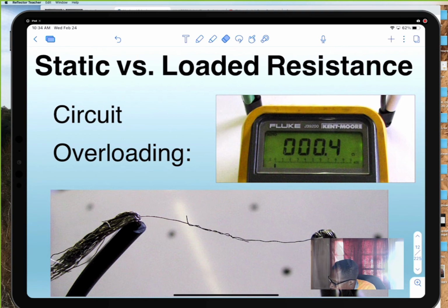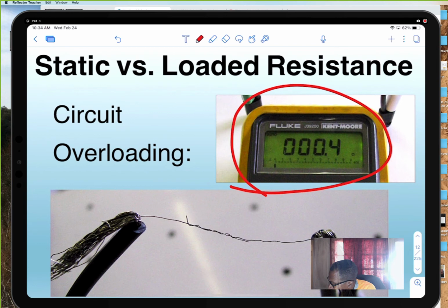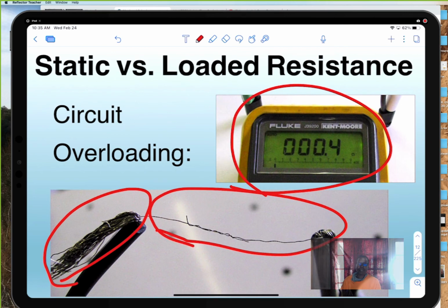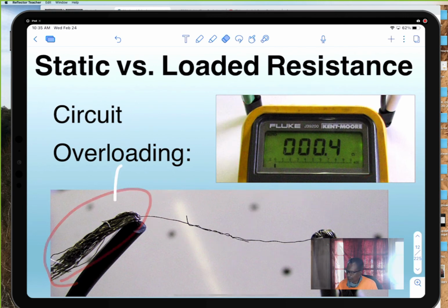But if you ohm it out, it's going to ohm out good. Remember, we have a lot of current running through this wire. All you're going to have is a real serious problem right there: it will heat up and cause resistance. And it's supposed to be like this, not one strand like that. Did I totally confuse you on that, or did you understand the relationship between that drawn and this?